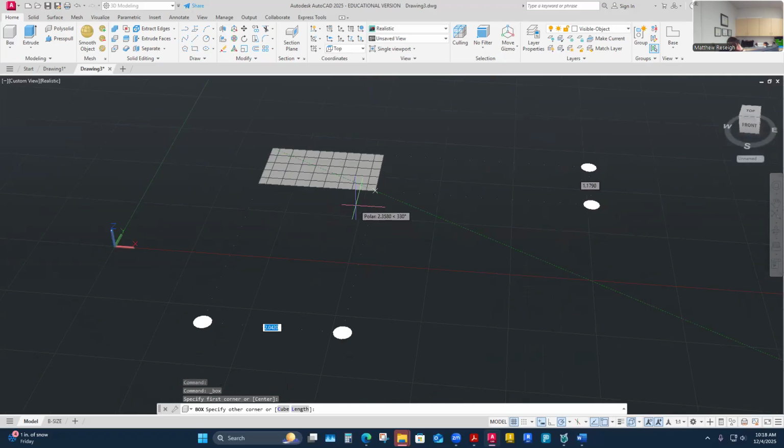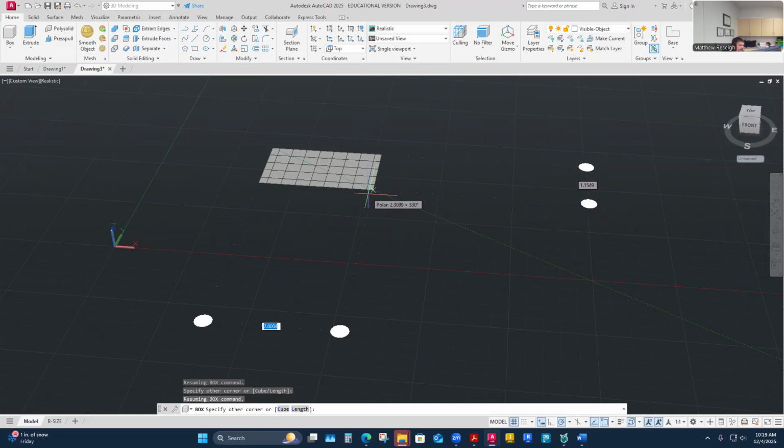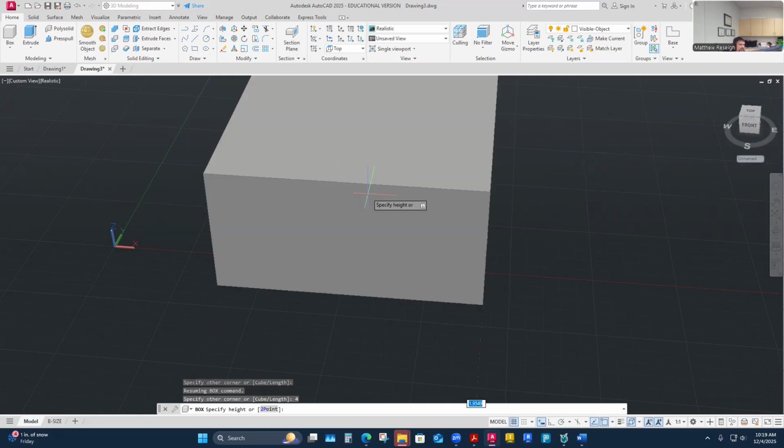I kept it the same as what fits on our drawing sheets without major scaling, like 3, 4, 5, 6 inch size stuff. A lot of the modeling we've done this semester so far has been in that size range. So I'll just do something in those similar size ranges, like maybe a 4x4 by something. It works the same way: this direction 4, sure. Tab, this other direction 4. So maybe I'm making a square base, enter.